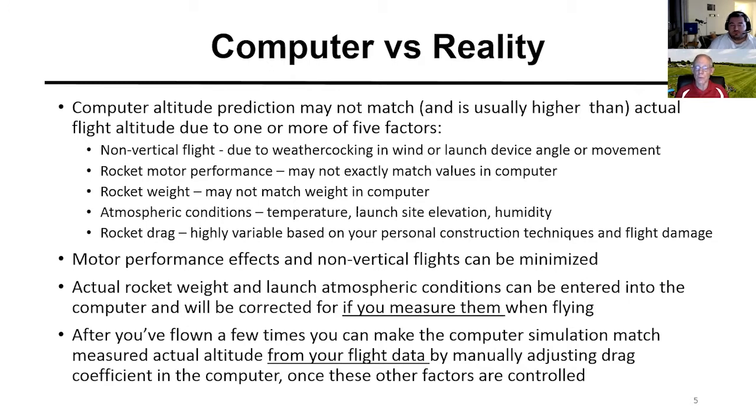The rocket weight may not match exactly the weight that you used in the computer simulation, and that's a rookie mistake. You've got to know what your rocket weighs and do flight simulations based on the actual weight of your actual rocket, including egg, altimeter, and everything. Simulations that are based on the wrong weight are completely useless. So you need to know what the weight of your rocket is before your simulation actually has a chance of matching reality.